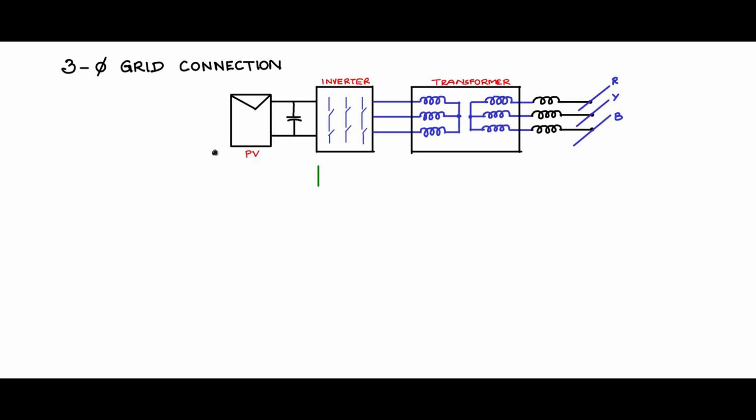Now the three-phase inverter, the gates, you have 6 gates, gate to source. Let us say I am using IGBTs or MOSFETs. The 6 gate drives have to be driven by a gate drive circuit, 6 of them like this. And the gate drive is getting the control signals from a PWM block in this fashion for the R phase, Y phase, B phase, or A, B, C phase.